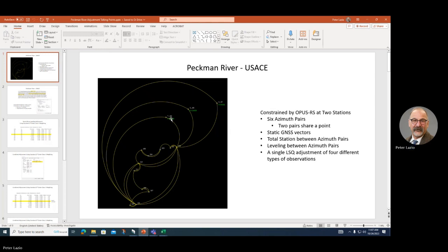But does Carlson allow you to do just the vertical translation without a tilt? Yeah, you can do either option. But with machine control, doing those localizations, I run into it a lot, where the dealers go out and do a 3-point localization for horizontal and vertical, and it's garbage. And they tell you, oh, it's perfect, see? You're vertical 0. What do you mean it's no good?